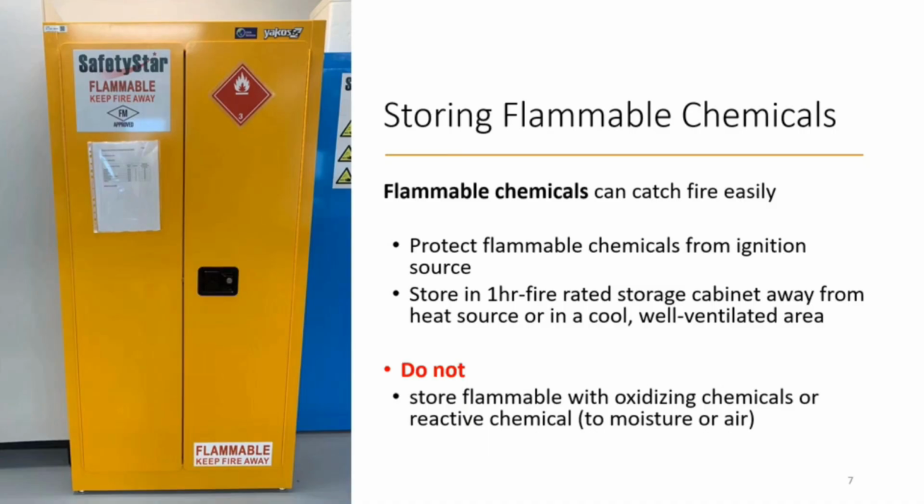A 1 hour fire-rated cabinet means that the cabinet can resist the exposure of a standardized fire for 1 hour. Do not store flammables with oxidizing chemicals or chemicals reactive to moisture or air, for example, pyrophoric substances, as they can cause the ignition of the flammable substances.